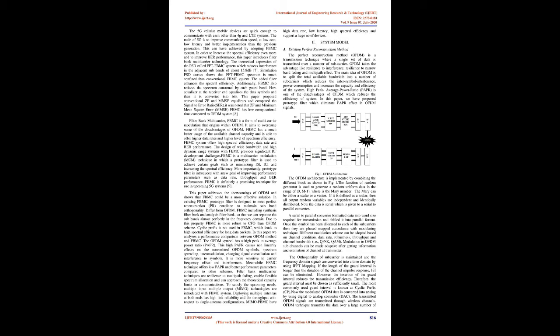In order to increase the spectral efficiency even more and to improve performance, this paper introduces filter bank multicarrier technology. The theoretical expression of the PSD, called FFT-FBMC system, reduces interference in the adjacent subbands by about 15.8 dB [7]. The simulated PSD curve shows that the FFT-FBMC spectrum is much more confined than the conventional FBMC system. The added filter enhances the spectral efficiency. Additionally, FBMC also reduces the spectrum consumed by each guard band.